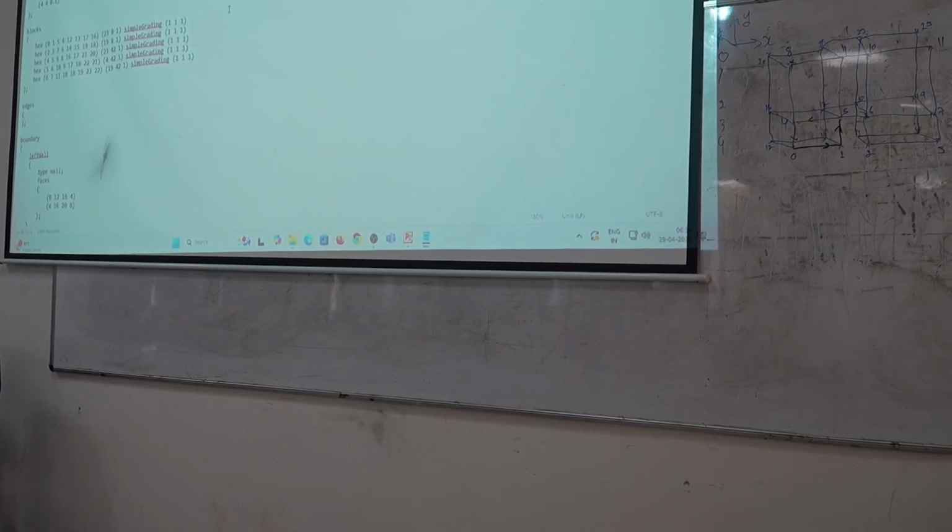So after defining geometry, we are defining how many divisions and what grid we want to use. This is a fixed Eulerian grid, and if we want, we can also use a dynamic grid, because the interface will be moving and the water will be suddenly collapsing. Would we not need to make it finer? Yes.